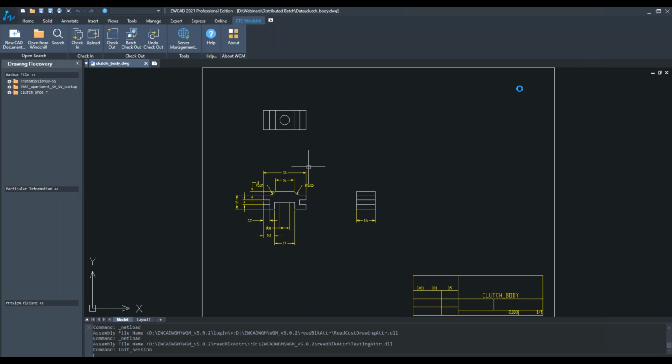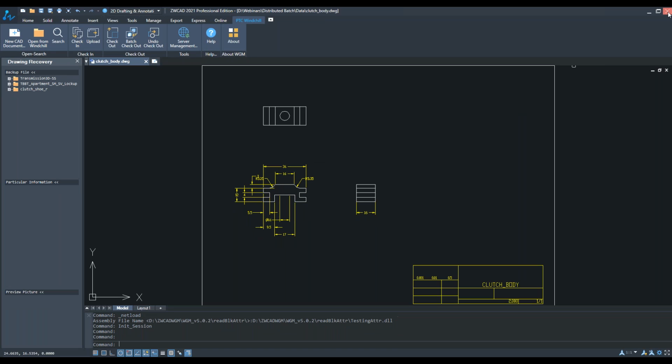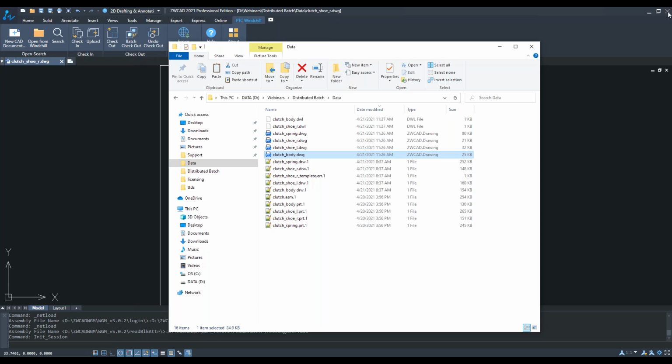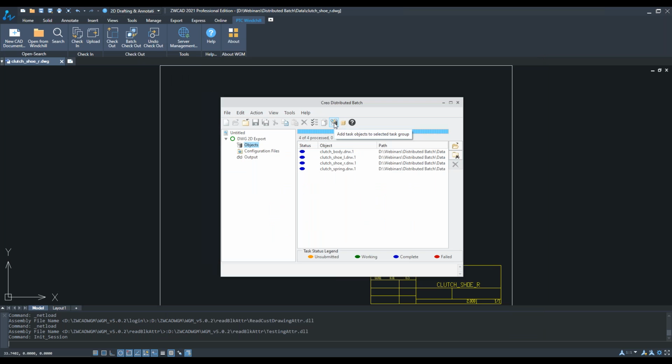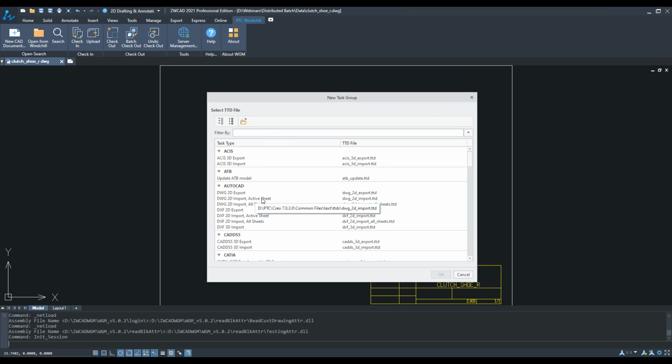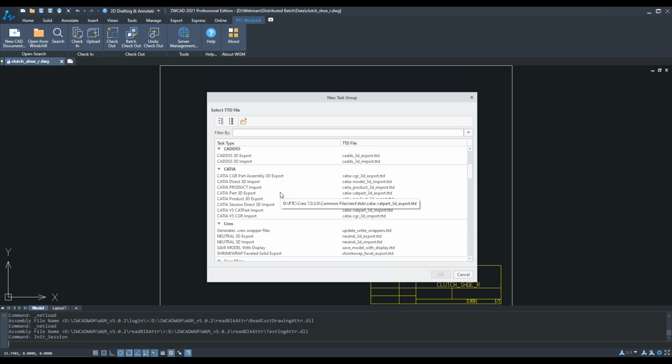If you know exactly what you need, an important bit is that TDD files, a lot of customers confuse that and don't really know how to apply them. So the important thing on the TDD files is to know where they are located, open them up in an editor, and then adjust them as needed, and then use them with a config.pro file.